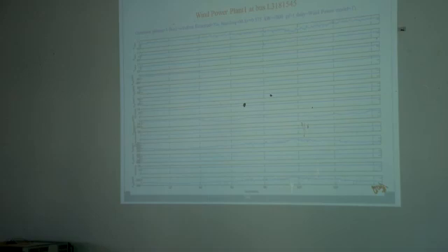So here these are the voltages at the generator, but how it is controlled and what kind of wind power model is taken here is mentioned here. In OpenDSS for wind power plants, certain kinds of models are there. Model number 1, model 2, model 3. It depends on what kind of technologies you are offering. Some generators are fixed speed generators, some are variable speed generators, but these are full speed operation generators. Some generators are partial speed operation generators like DFIG. So depending upon that, there are 2 to 3 models of wind plants in OpenDSS. So here we have used model number 1.